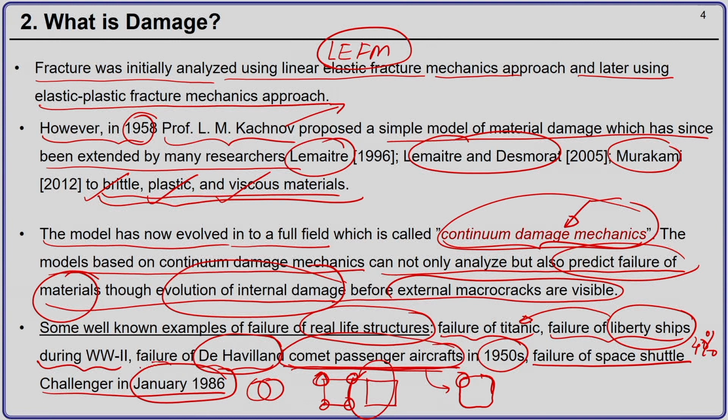But in January 1986, when the shuttle was launched, the temperature that day was very low, something like 4° centigrade, and at this temperature the rubber O-rings became very brittle. So, there was a transition of the material from ductile to brittle, which caused the catastrophic failure of these O-rings, which led to the escape of hot gases and fuels which mixed, eventually leading to the blast of the Challenger, and all 7 lives were lost.